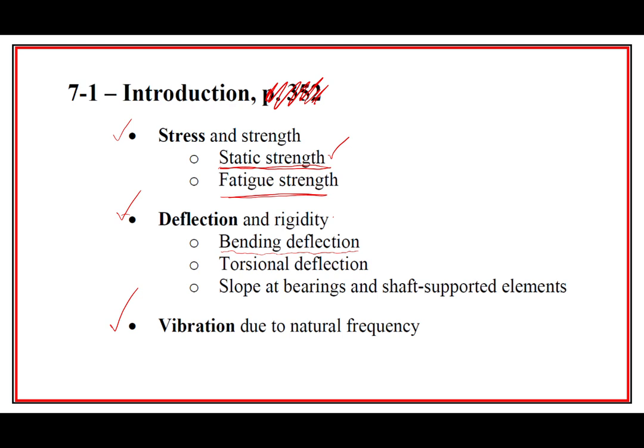It also might have some kind of deflection issues in terms of the surrounding equipment or even the housing. You might need to design it so that it was a fairly close fit, and so there's not going to be enough gap between the edge of the gear and the housing. If the shaft is too flexible, you could rub up against the housing. That type of idea in the deflection. We want to double check it's not too much.